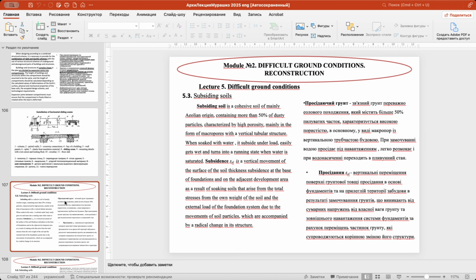It can be a rigid scheme, it can be a ductile scheme, and it can be a combined scheme, which gives an opportunity to connect various rigid parts of the building with a ductile connector between them, so that when uneven settlements of soils take place, it will not lead to progressive collapse of the building. We will only see that one part of the building settled down more than the other one, but no catastrophe, no problem, because this uneven deformation was taken by that ductile connection.